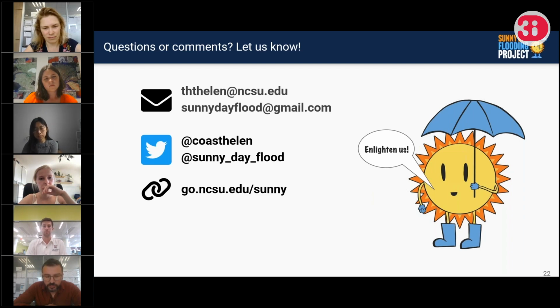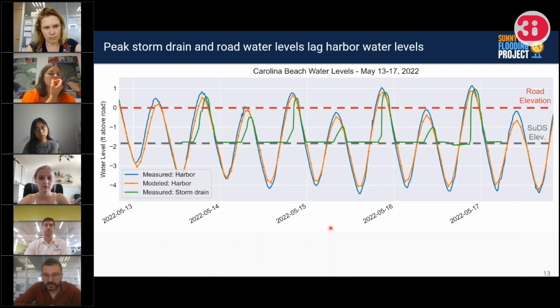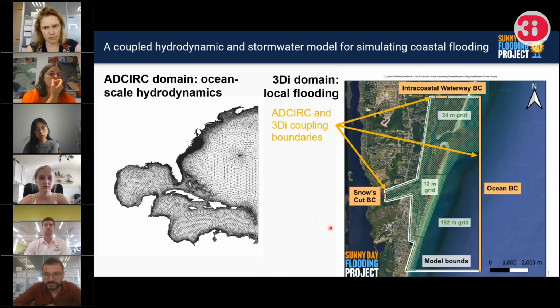Have you analyzed what could be the influence of the wave height? Because basically with ADCIRC, you are not simulating wave height, and in the coupling, you are usually going with water levels. But then I was seeing your graphics and they fit pretty well. So there is no underestimation of the water levels, basically, that in other kinds of storms could happen because the waves are not simulated. Can you have a small comment on that?